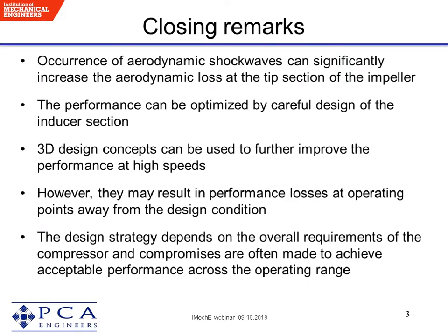Well, it's quite possible to use some form of thin casing which is closely spaced to the impeller, and I suspect by adjusting the temperature of that or by injecting flow onto the back of it, one could adjust its shape to control the clearance, but I don't know of any published work on that at all. Hamid?